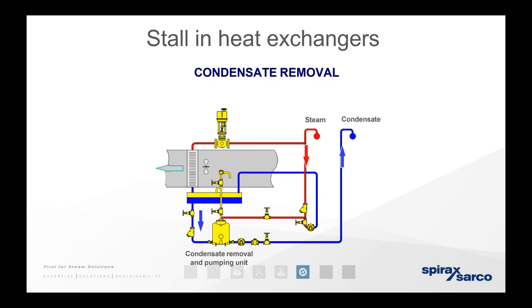So, condensate removal. As we have here, there's a pumping unit at the bottom of the heat exchanger. It's still the air system, with the control valve coming in at the top. Your primary is filling the air handling unit, the AHU. On your secondary side you have a vessel to hold the condensate so you don't get any flooding, down through your traps and strainers into a pumped unit, which then sends the condensate back. Into the pumped unit, the red line is a motive steam line.